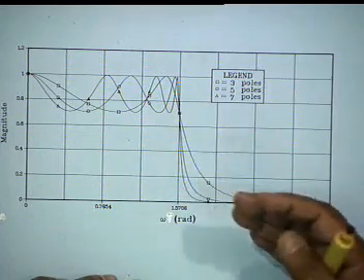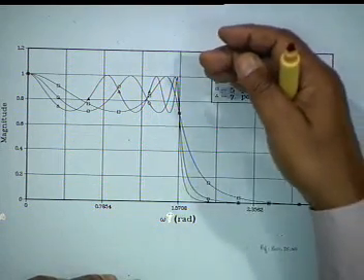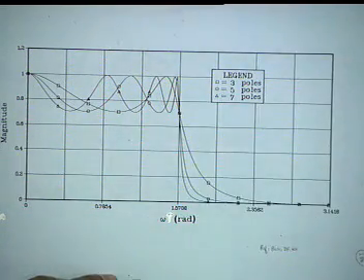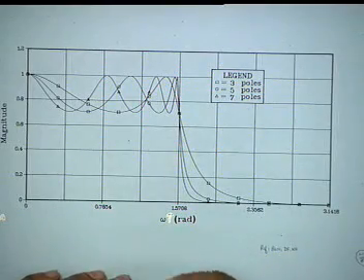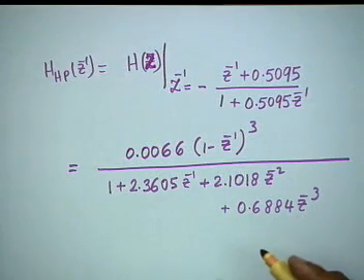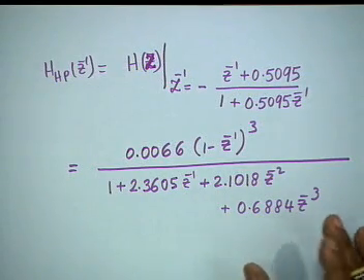It's just out of curiosity that 5th order and 7th order responses have also been plotted. No change in the pass band tolerance. It is only the stop band that we over satisfy. Pass band is sacred. You also see the number of ripples increases as the order increases, okay? Now, about this filter, I shall show the magnitude response a little later, but there are several things to notice.